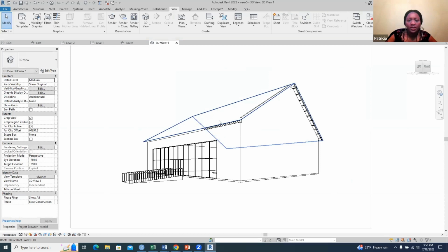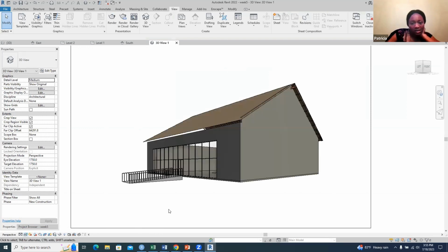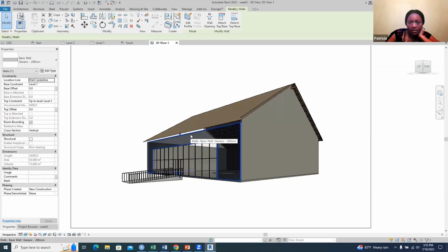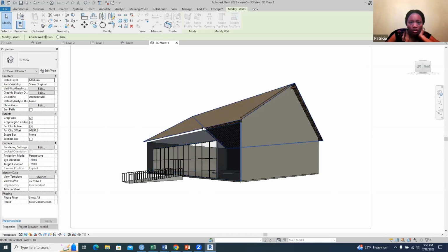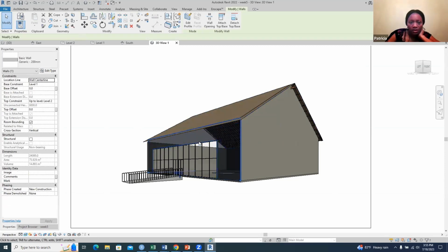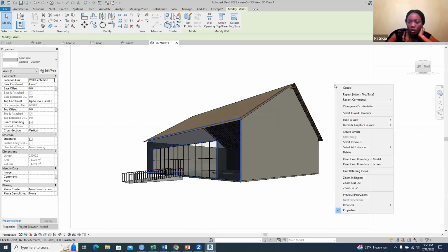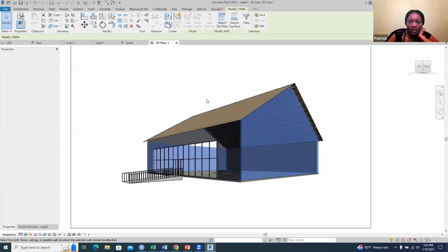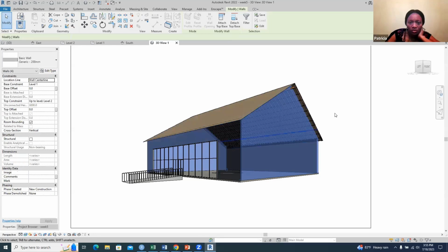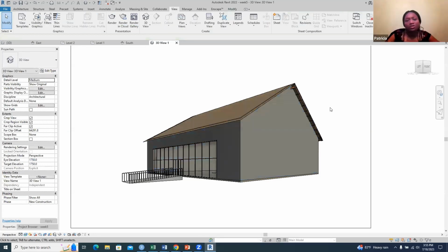So in Revit here, each view you have to go and select how you want to see it. So if I pick a realistic, this way, I can select this, attach top to the roof so that we're not seeing skies, and select all instances in the projects, and then we attach the top to the roof. Okay, so when we have this, we can go to this render.